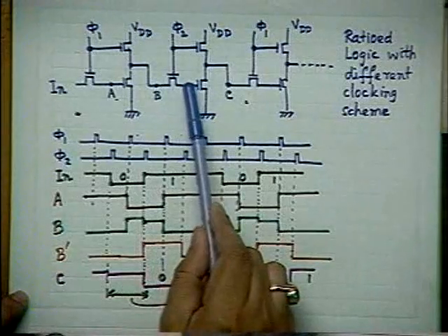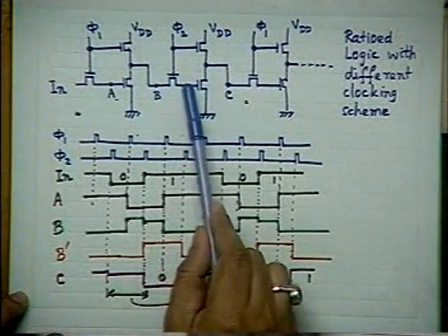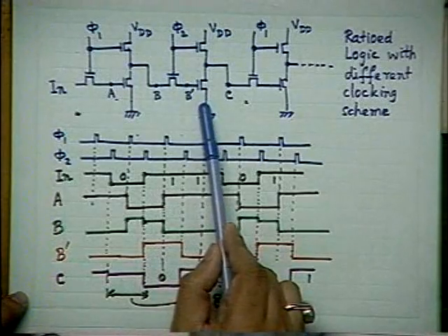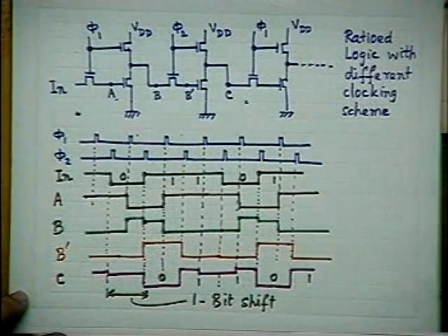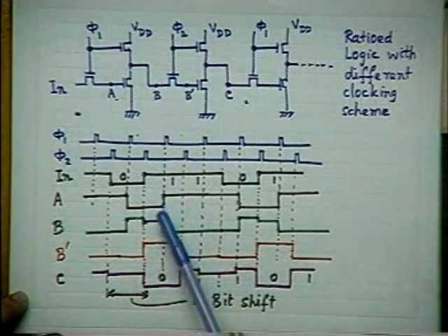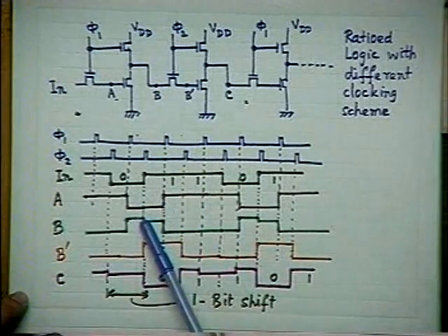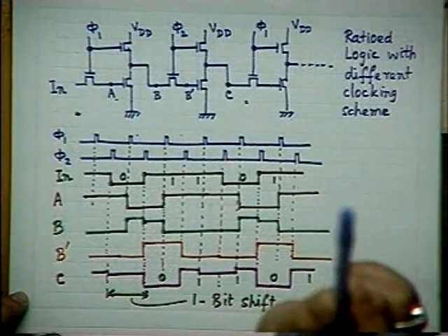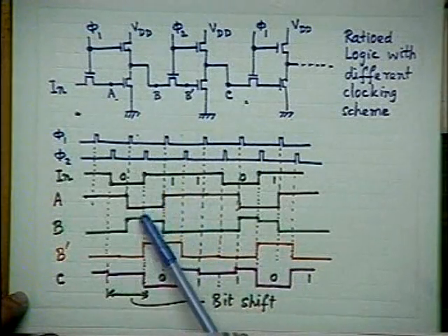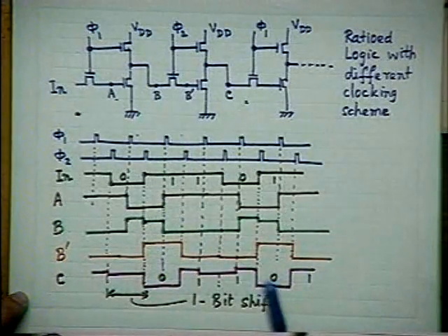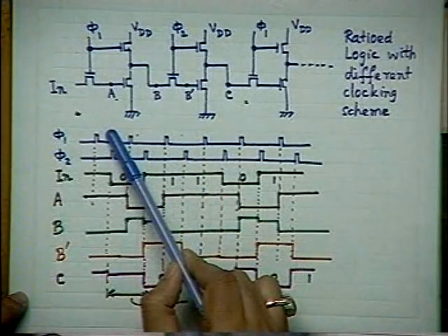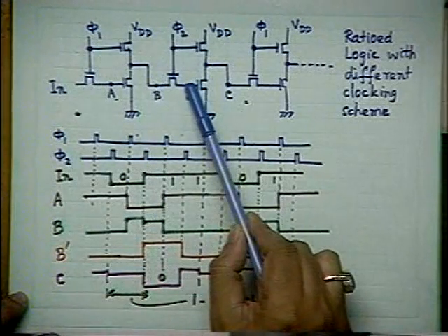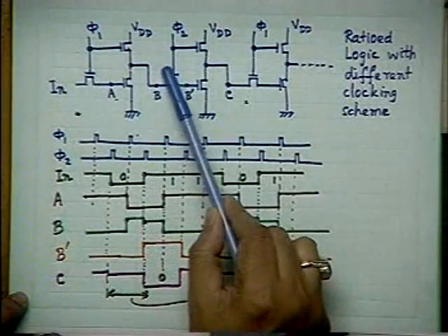This thing happens very quickly. So what will happen now? This charge distribution loses only a small charge to fill up the capacitance properly. That means to charge this capacitance to the proper final voltage. So naturally, as a result, the voltage at this point will not fall much. At this point, I'm not speaking of the point at B dash, but at this point B will not fall much if I can maintain the condition that the capacitance at the node B with respect to ground is large compared to the capacitance at the node B dash with respect to ground when this transistor is off.